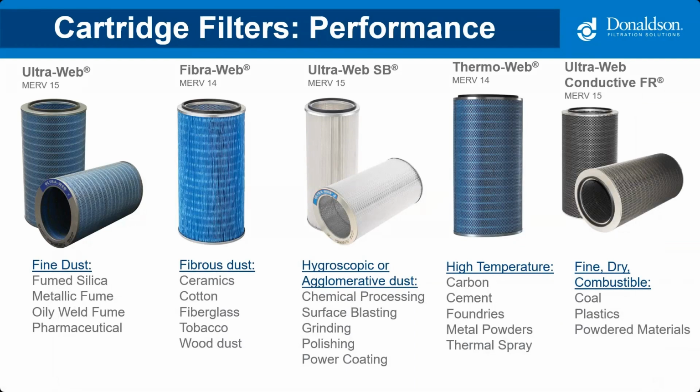For example, if the dust is fibrous and you're specifying a cartridge collector, you're going to want to specify fiber web media or something similar with large pleat spacing, or the customer is going to have issues. And if the dust is conglomerative, you're going to want to specify a cartridge filter that has spun bond based material, or the customer again could have issues.